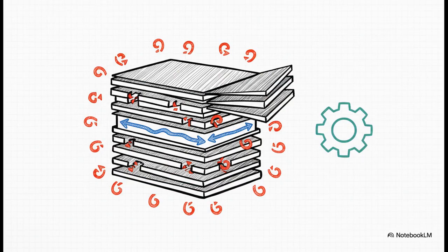And this is just a brilliant bit of engineering. Instead of using a solid block of iron for the core, it's actually built from thousands of very thin sheets or laminations. Each one is coated with an insulating varnish. This structure creates a really high-resistance path that effectively blocks those eddy currents from flowing, which drastically reduces heat loss and massively improves the transformer's efficiency.